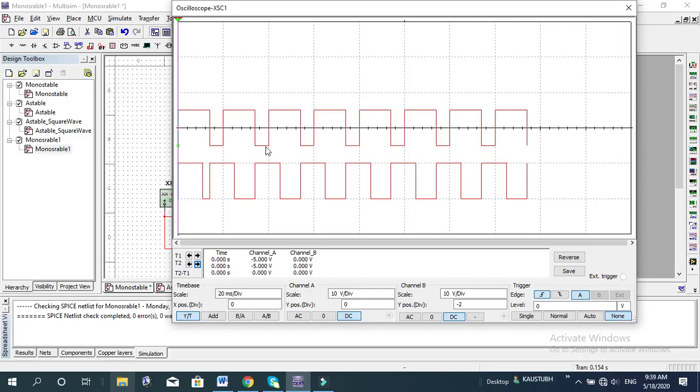So that can be useful for blinking of LEDs, because often this narrow pulse, suppose with this pulse, if you would like to display an LED, often these narrow pulse signals are not suitable for driving an LED display, mainly because of their very narrow pulse width. In other words, the LED may be flashing, but it may not be visible to our eye. So we need to stretch out this pulse. Okay, so this pulse stretcher can be used to remedy that problem.